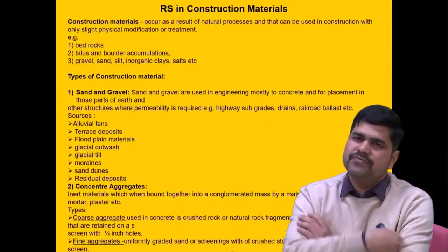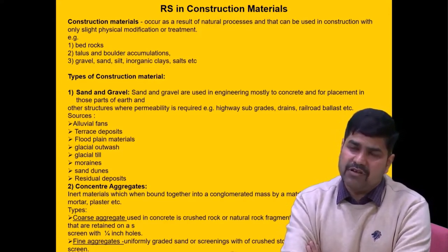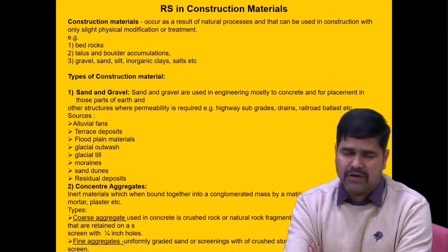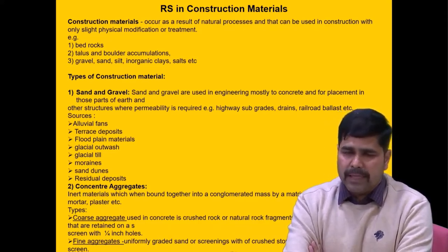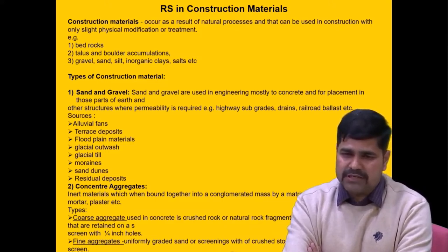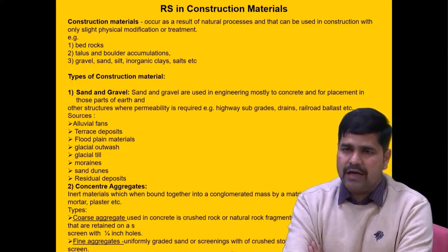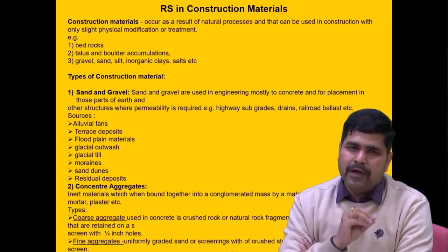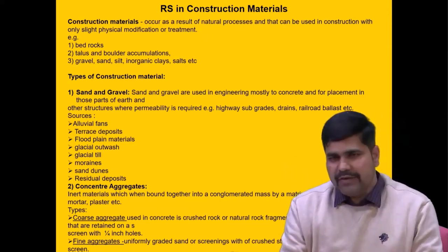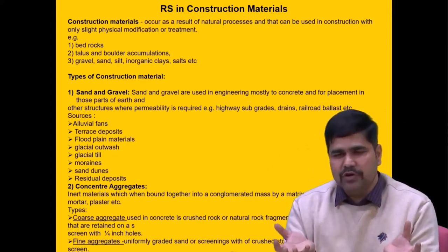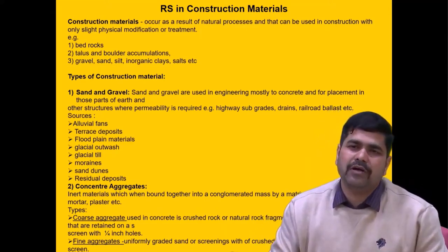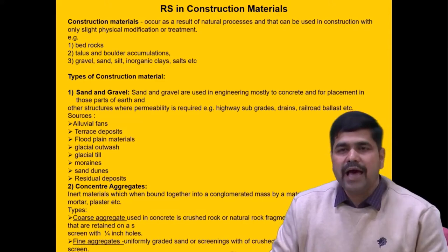Another application of remote sensing in engineering geology is tied up with construction materials. You know what construction material is? Suppose we are constructing a dam, or a powerhouse, or a road network. If a dam has to be constructed, some material is to be blasted, and along with concrete, some material is to be put. Why bring it from far off places? Along the river bed, whatever is available, the cobbles and boulders, take them and bind them together with the concrete. So the material that is available there is readily consumed as construction material.